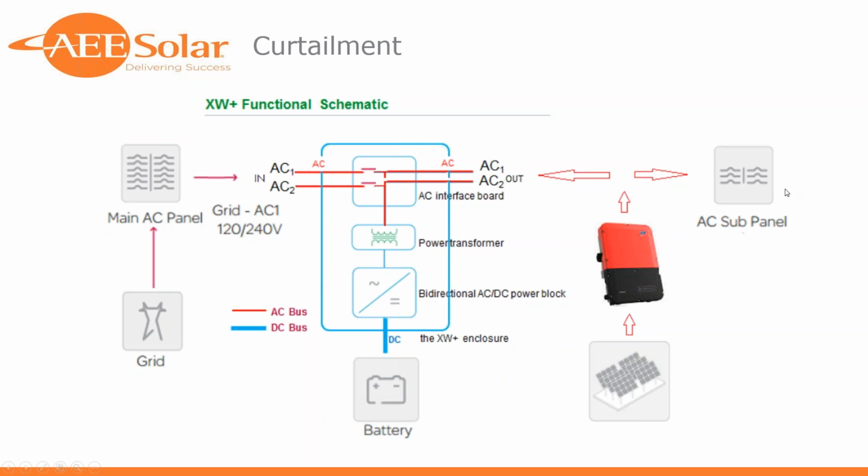So if these relays are closed, it's going to sync to the grid that's supplied from the utility grid, provided it falls within the qualifications as established by UL 1741 or 1741 SA. So if the inverter sees a qualified grid, great.